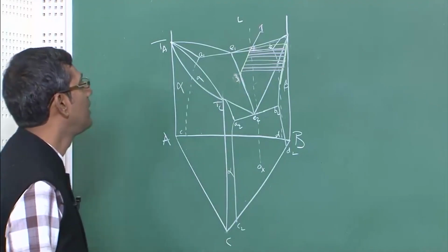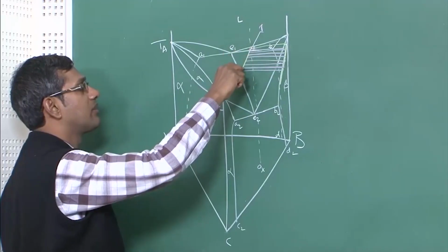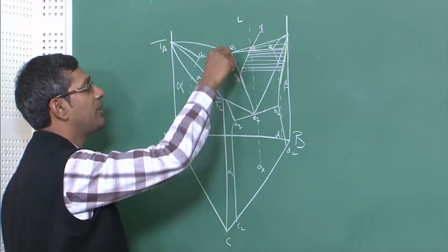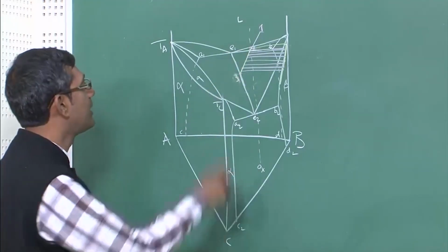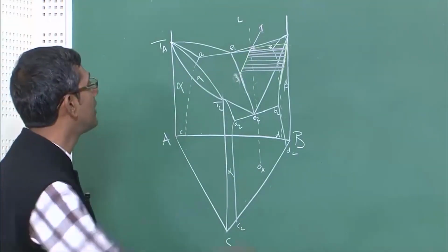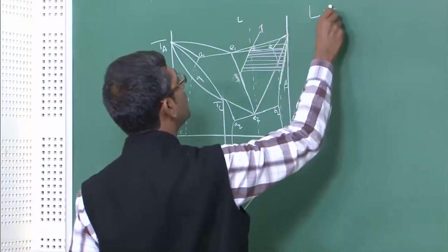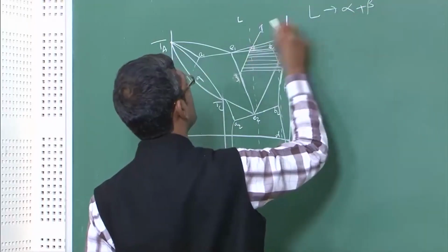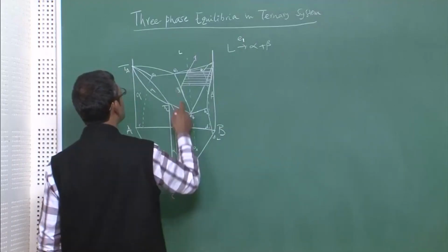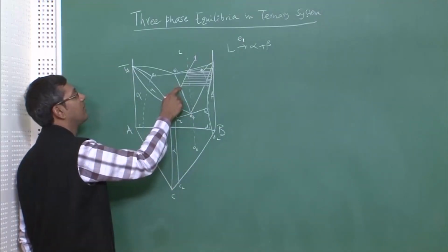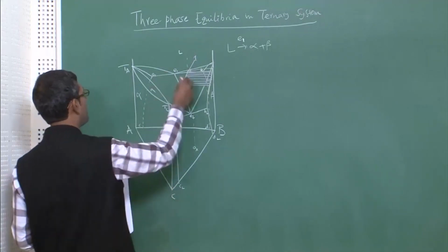At point 3, this curve on the liquidus surface will touch the surface at E1, E2, you can see here, this is going to touch that, and that means that this will precipitate also alpha, because this is the eutectic, and the eutectic reaction is what, liquid going to alpha plus beta, right. This is the E1 reaction, E1. So, because of that, this is going to precipitate alpha also.